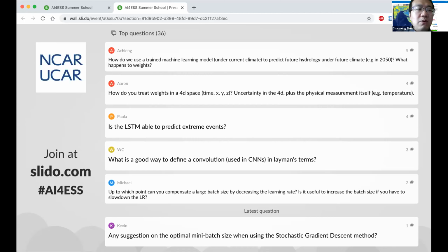So if you train your hydrologic model in the current period using the real climate data, and then when you forecast, you project into the future using a climate forcing, those two are characteristically different. Like the two are coming from totally different background distributions. Because if you run the climate model now, for the current decade, it's not going to give you the current climatology. So I think this question sounds simple, but actually has many turns.